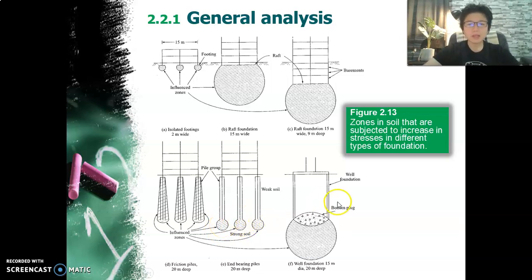And the last example we are looking at is a caisson, or the wall foundation. This kind of foundation is a huge pipe, and it's empty inside, and it's very commonly used in what? Yes, you guessed it. It's very commonly used to build bridges, alright? Penang Bridge, Second Link, and so on and so forth. And how they construct it is that first they have to drop this big, huge, heavy, usually a concrete or a steel pipe into the seabed, alright? Make sure it's aligned, and then they suck the water out.